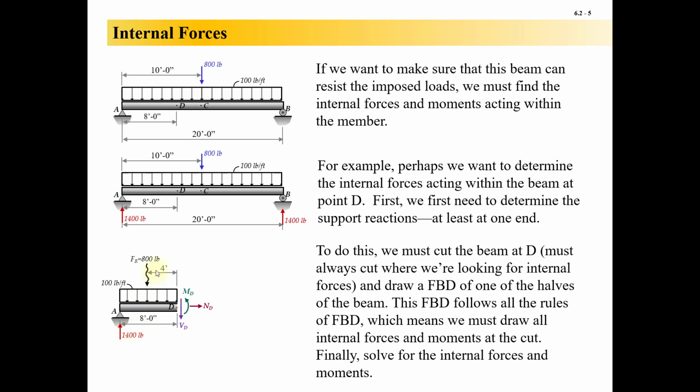And so now you can see that we've got our support reaction that we had calculated already, and then we find the resultant of this distributed loading here, and that's here, and then we can solve for these internal actions using the same equations of equilibrium that we're used to. So in this case, we would end up with these values.